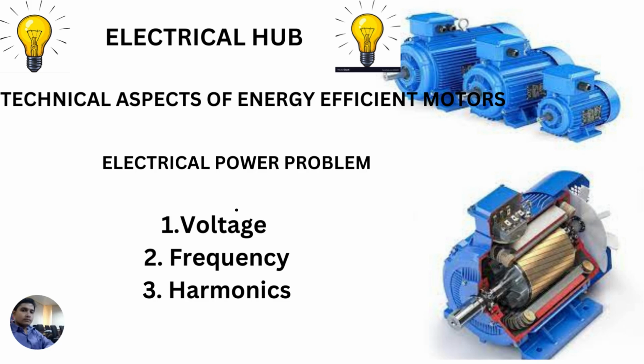Due to the increase in the operating temperature, there will be a reduction in the life of the motor because every 10 degrees centigrade rise in the operating temperature of the motor will reduce the life of the motor by half. Number 2, frequency, and number 3, harmonics. Both are interrelated.